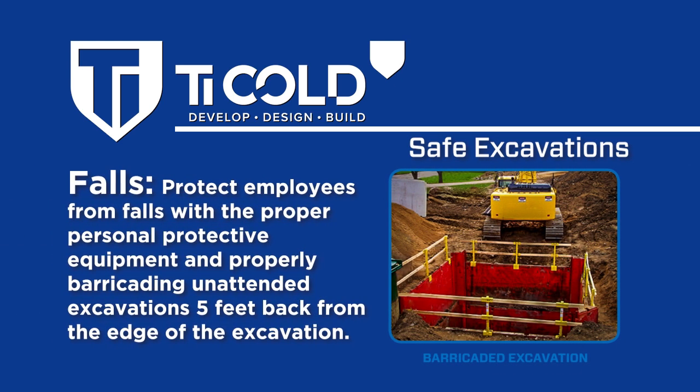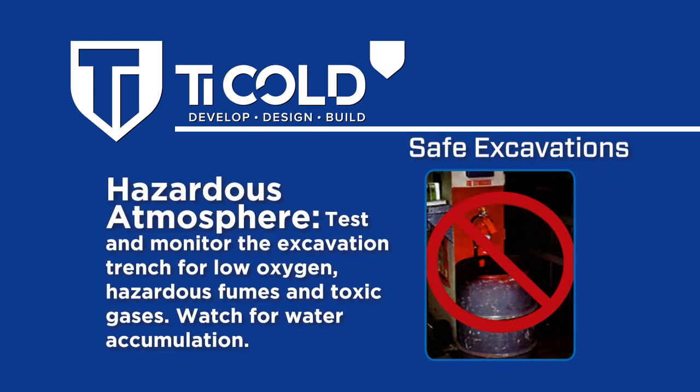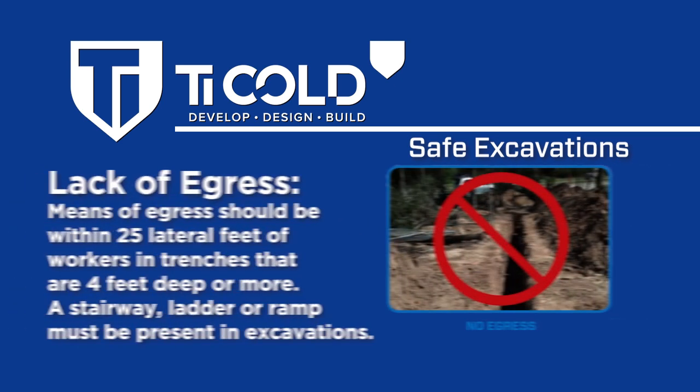Falls. Protect employees from falls with the proper personal protective equipment and properly barricading unattended excavations 5 feet back from the edge of the excavation. Hazardous atmosphere. Test and monitor the excavation trench for low oxygen, hazardous fumes, and toxic gases. Watch for water accumulation.